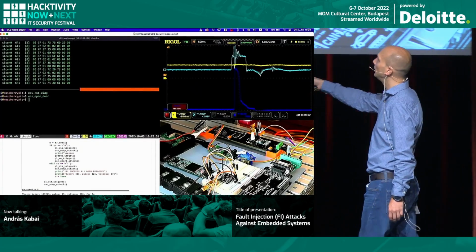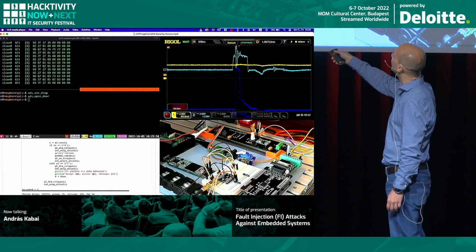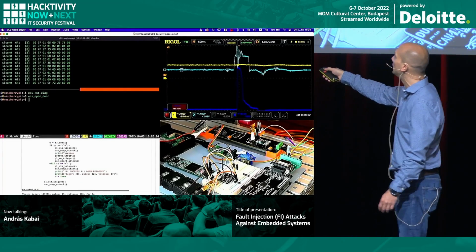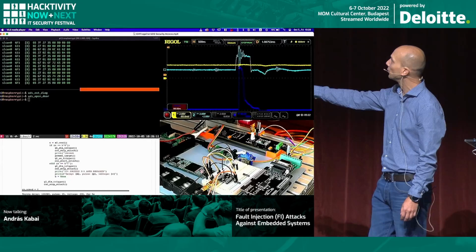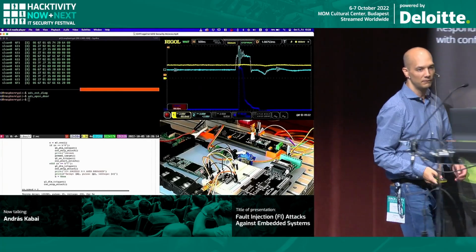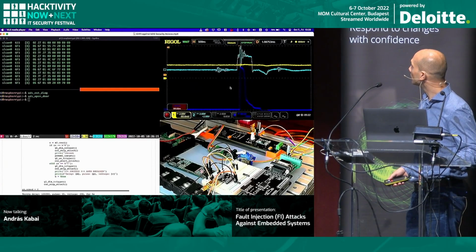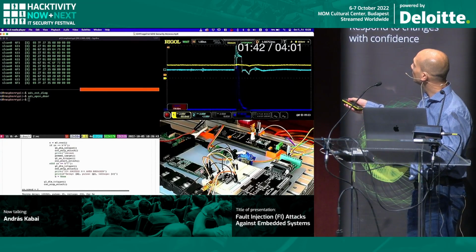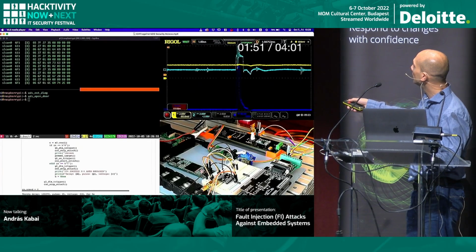We are continuously monitoring here what is happening on the CAN bus. And as you can see the patterns, basically 2701s are sent out, then we receive different seeds. Then 2702 with a fake key 1234 is sent out for authentication probes. And basically we always receive 7F error codes that authentication was failed until, if you zoom out, you will see that compared to the trigger, there's a lot of time that passes before we execute the actual attack.